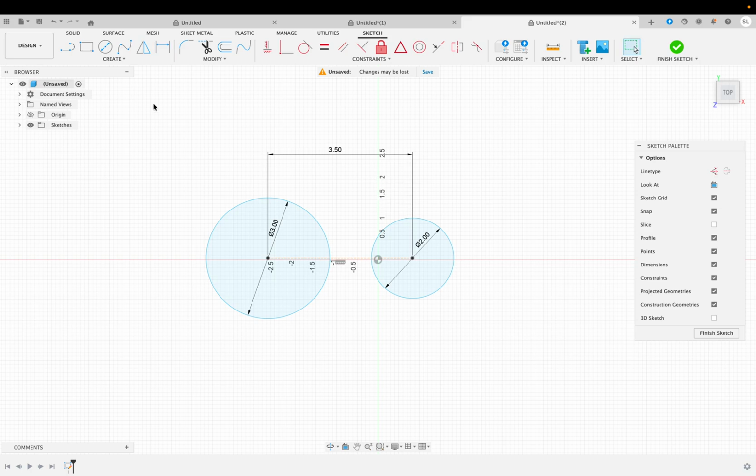All right. Now, put the lines between the two circles, there to there. When this crosshair comes up, that means it's on it. That's what you want. And then here to here. And then again, geometric constraints, you want to do tangent. Select the line, the circle, line, circle. The little icon means that there's a constraint.